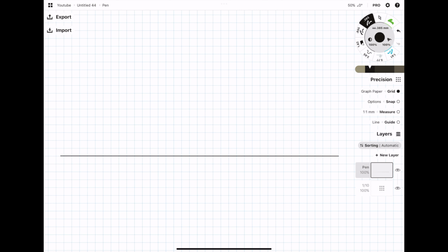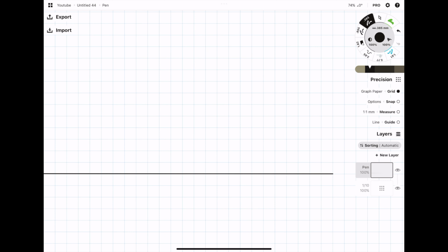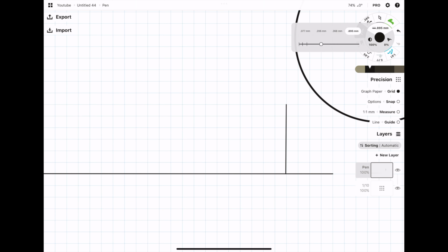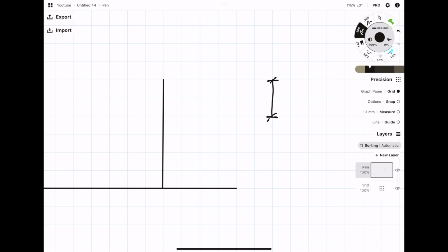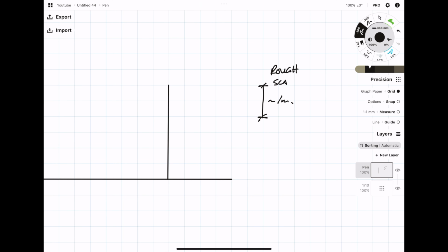By drawing the section firsthand, you actually get a very good understanding of the problem or the situation that you've got. When I do a sketch section like this, I probably won't be sketching to scale, but it's going to be a rough scale. So in this sketch, every 2 squares is going to be roughly 1 meter, and that's what I'm going to be kind of basing the sketch on.